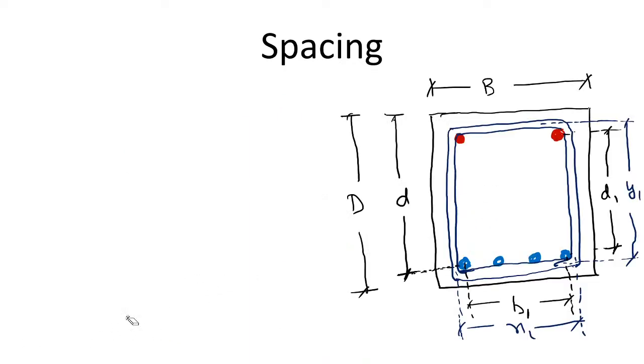Okay. So once again I am reminding you guys, before proceeding to the calculation of shear stirrups, first of all you have to assume the suitable diameter of the tension reinforcement, compression reinforcement, shear stirrups and all. You have to assume something. Okay, then only your B1, D1, X1, Y1 will be crystal clear. Don't worry, we will take a numerical on this. So shear is also clear now.